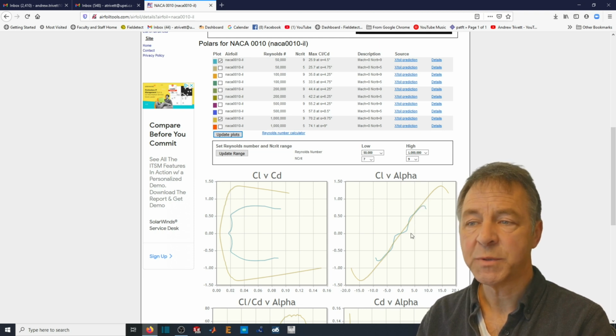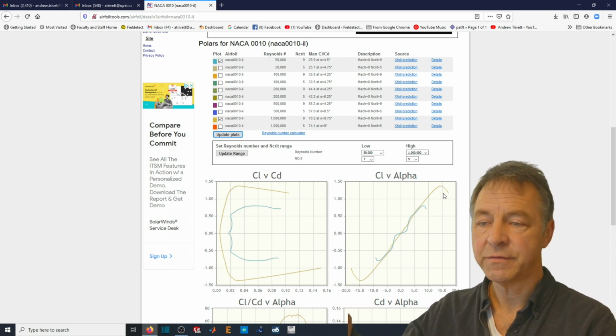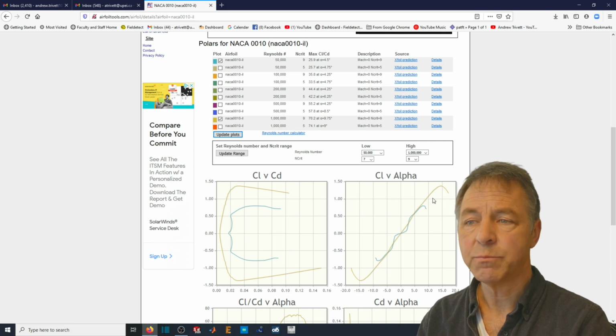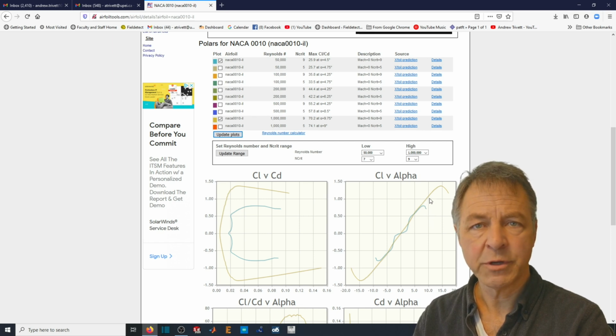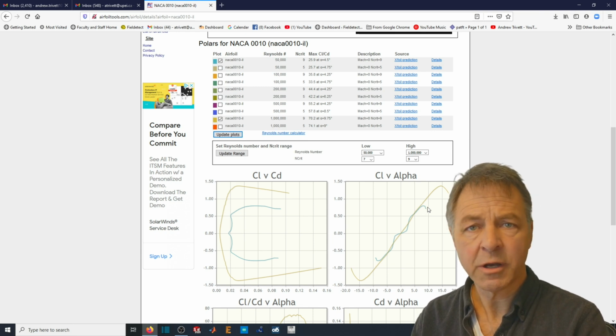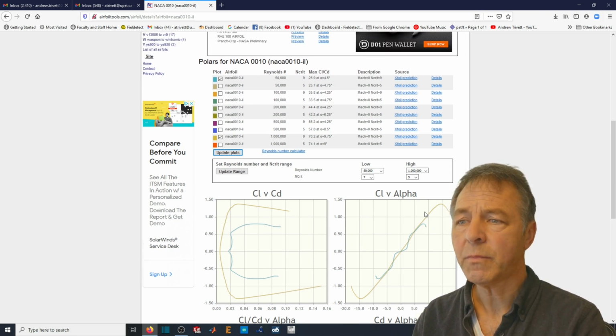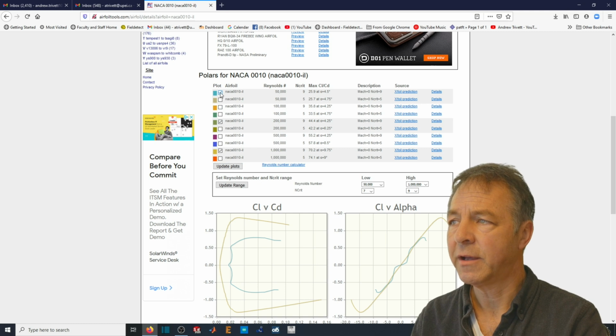Whereas at higher speeds, that same airfoil would be good to a pitch angle or an alpha of 15 degrees. That's a massive change, and it means that at low speeds, this airfoil is very, very critical to its angle of attack, which, if that was a passenger airplane, could cause real problems. So we have to know what the Reynolds number that we're looking at will be.